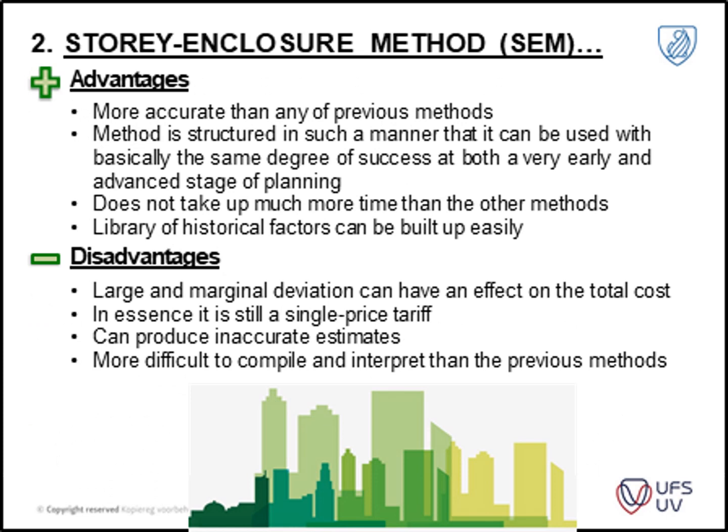So the storey enclosure method: the advantages are that it's more accurate than the previous methods. The method is structured in such a manner that it can be used with basically the same degree of success at both very early and advanced stages. It doesn't take up much time, and that's the biggest advantage of this method. And the library of historical factors can be built up quite easily.